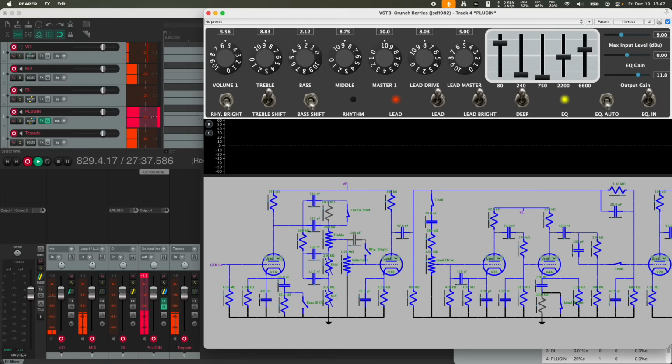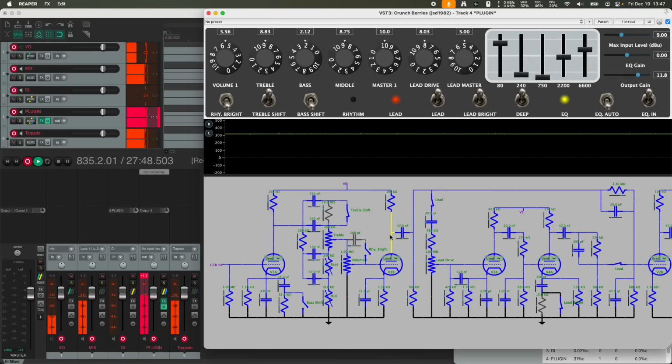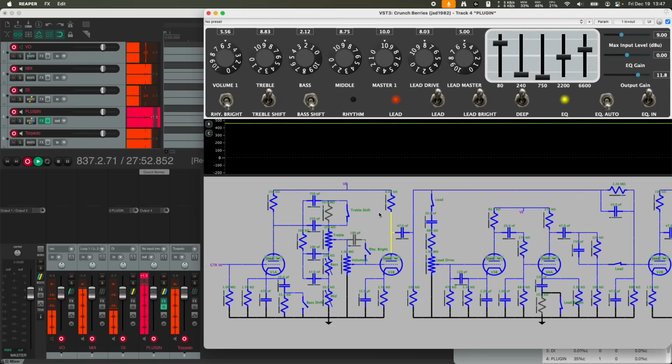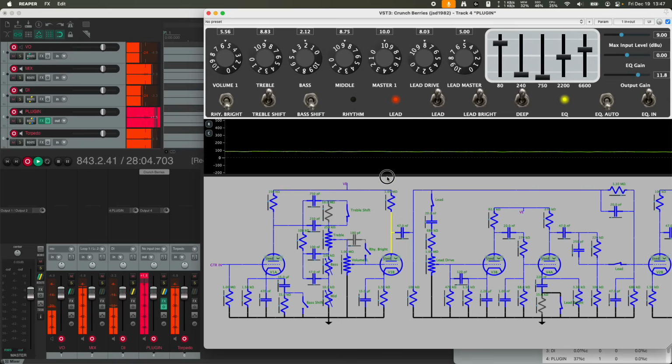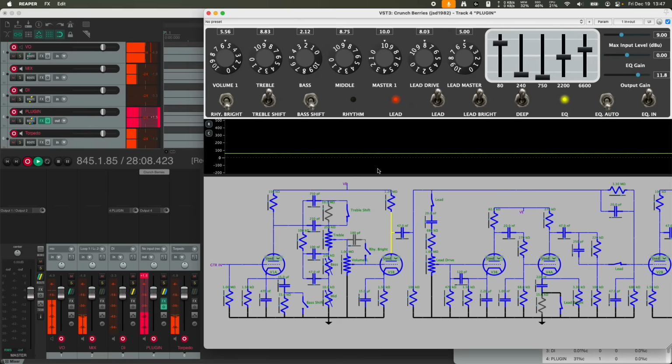And of course, we can play with the resistor that feeds the plate, and that can change the DC offset. So we can take a look at this. Sorry. Let me show you that. Yep. So a lower resistance brings it closer to our reference voltage, which in this case is 500 volts. And then more resistance brings the DC offset down.